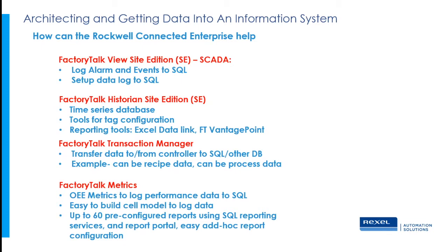And talking about Transaction Manager. This is a software package where you're just configuring transactions to transfer data back and forth from a controller to SQL or other ODBC database. An example could be recipe data. It could be process data as well. It's bidirectional, as you'll see.